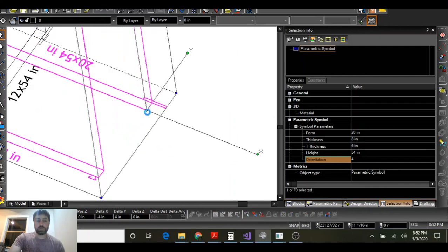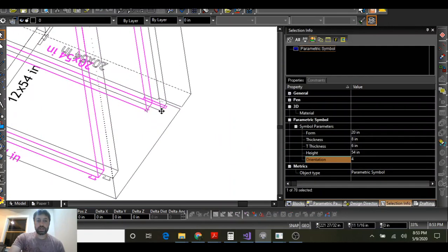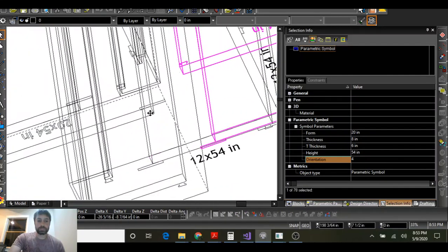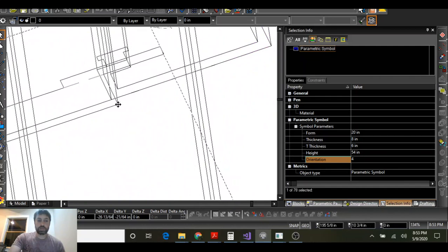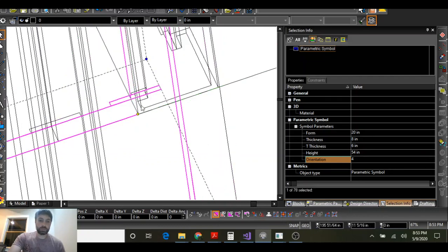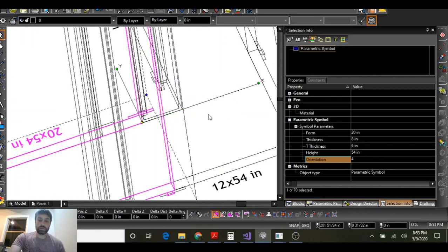What I'm doing with this little yellow dot in TurboCAD, this is a reference. It just gives me the ability to make sure that I'm dropping this form part, this parametric part, precisely where it snaps. Where I'm snapping right now is the inside corner of the previous, or the corner piece right before it.